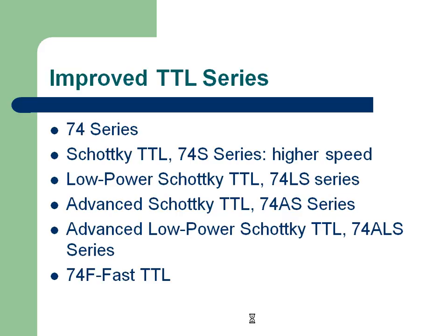Within the silicon, the important quality that we are looking at is density. That is, we should occupy smaller silicon area and realize a Boolean function with acceptable power and delays. CMOS proves to be the best choice. NMOS and PMOS alone have power problems; they burn more power, while in CMOS the area is bigger. So when we talk about the speed-power product, CMOS becomes a good choice. CMOS logic, analog and digital variants, is the dominant on-chip design logic. So in our subsequent topics, we will talk only about CMOS. We will not talk about the others.